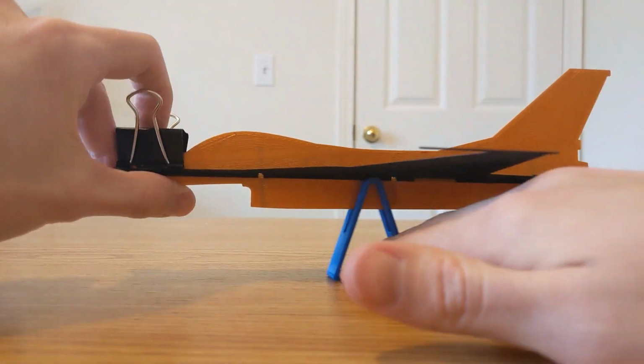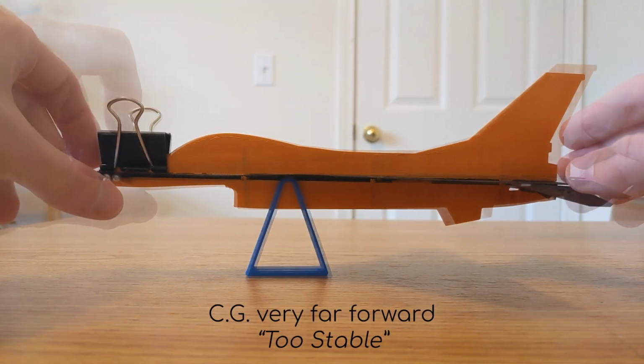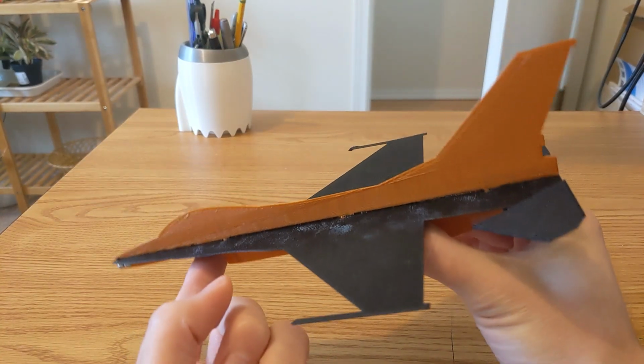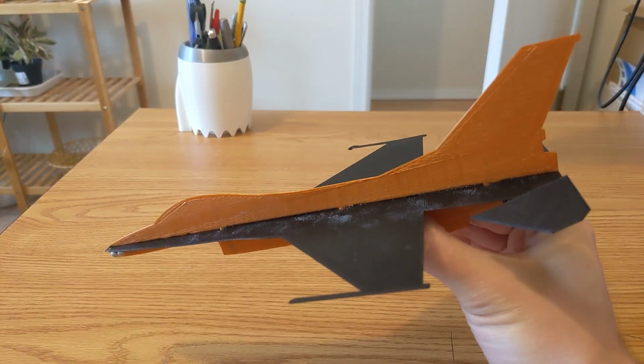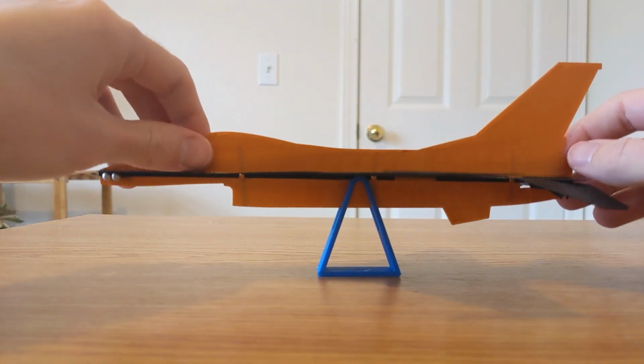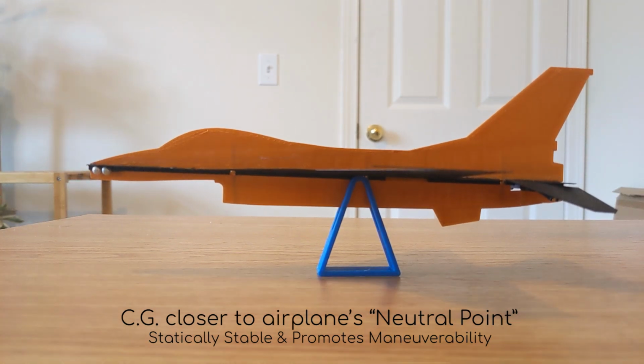If the CG is too far forward, the airplane will be statically stable, but too stable, making it so the horizontal stabilizer does not have enough pitch authority to keep the nose of the airplane up. For an RC airplane, you want the CG to be at a good spot that provides enough static stability, yet good maneuverability.